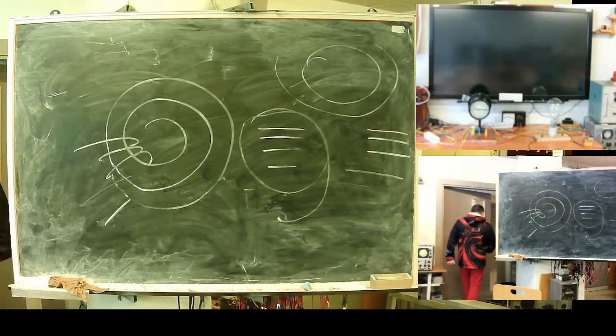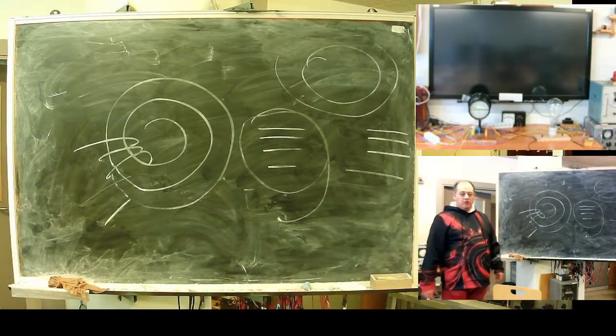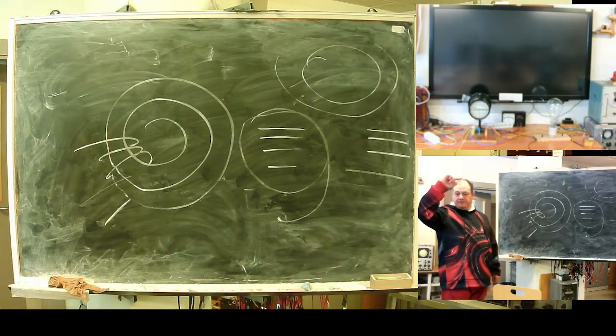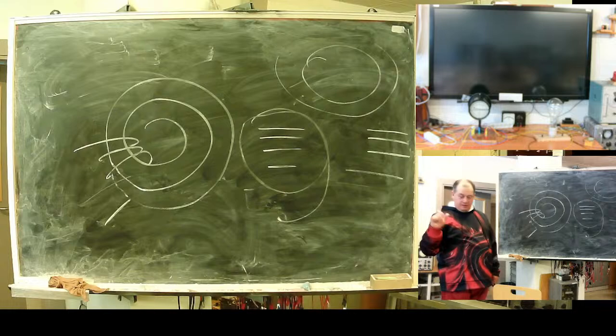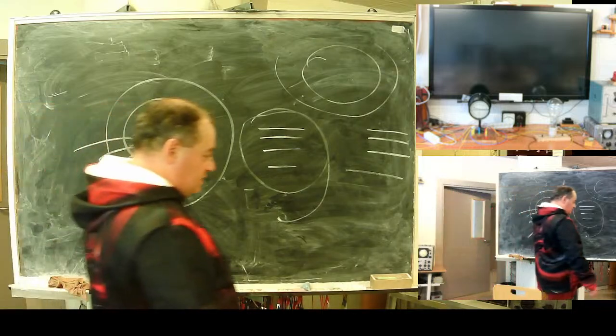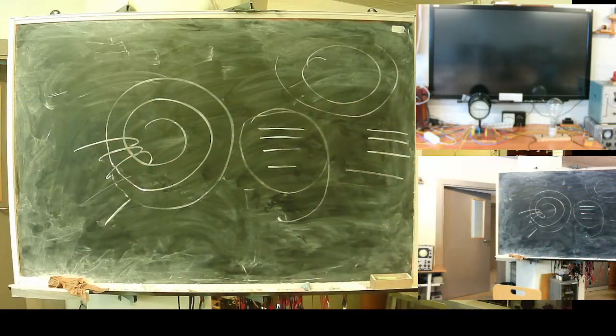So with current transformers, you always have a problem with saturation, limiting at the high end, and non-linearity at the low end. And at low end, you will always have an error because of leakage current.